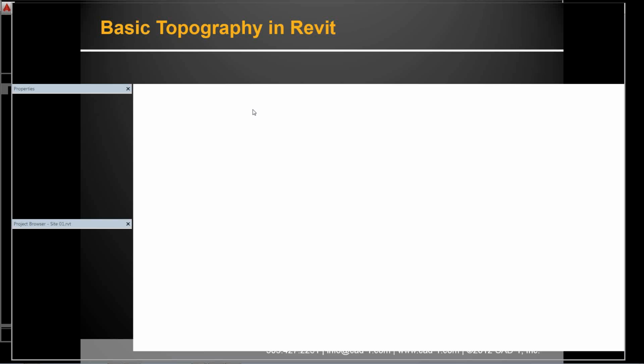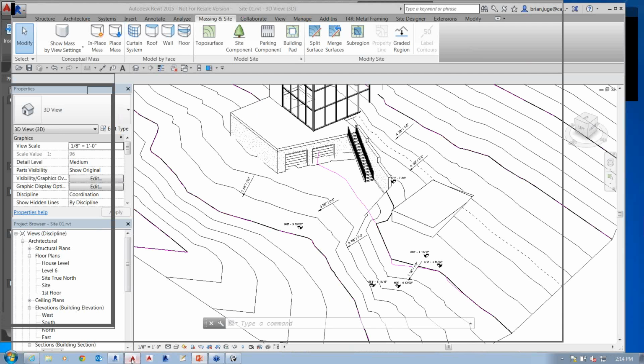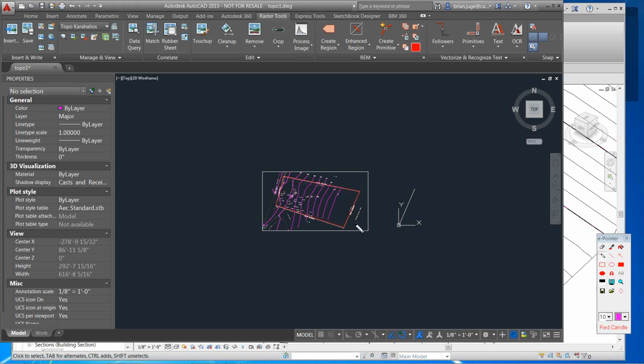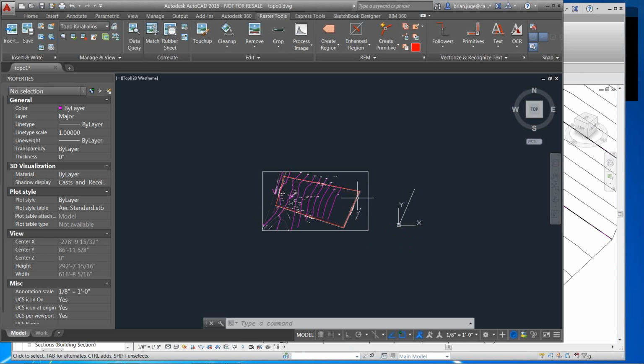All right, so help. Rick, we're going to go back here to AutoCAD, and this is where you have to start. If you're bringing that file in and it's outside the 20-mile range, you're going to get an error. Hands down, it will not give you the topo stuff. We're going to have to go in and relocate this file to get it close to the origin in here. Now, one of the things that we can do is manually move this and clean up the file. That's kind of what I did in here.